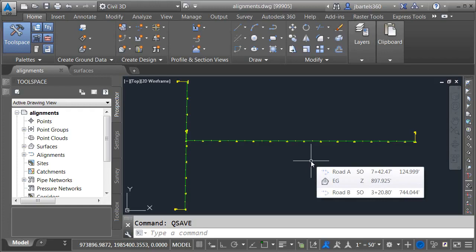That being said, if a data shortcut link gets broken, it can affect every drawing in the project that depends on that link. So in this session, we are going to create and then break some data shortcuts so we can explore different ways to restore the connections.